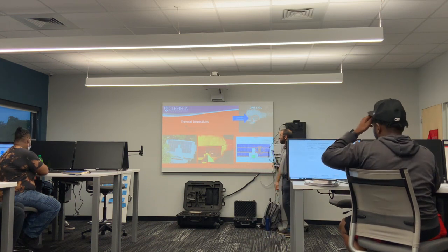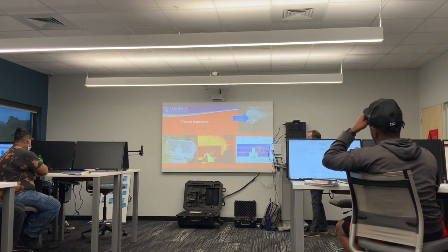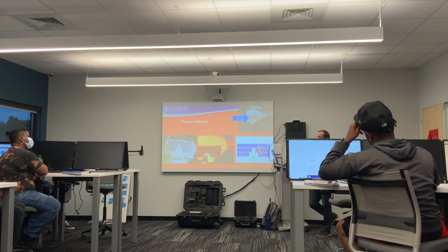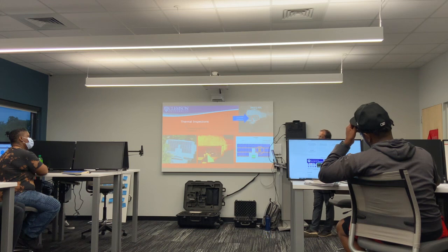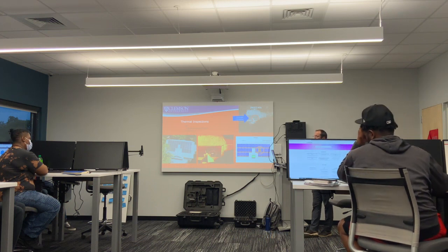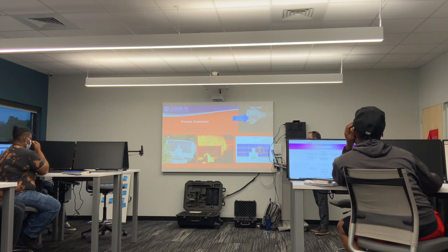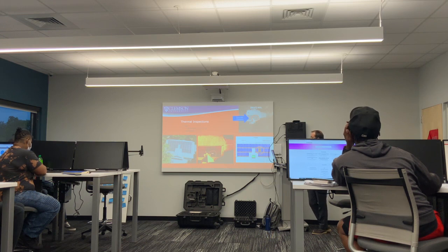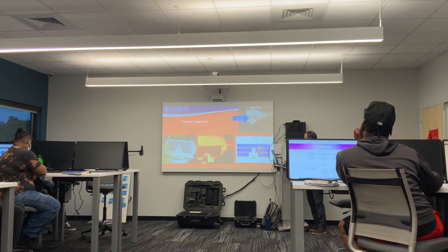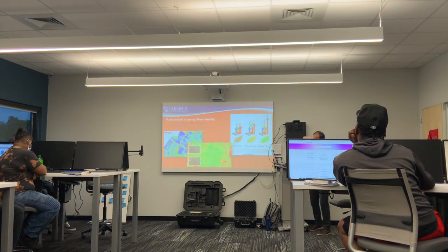So very interesting. He estimated, based on solar panels that he flew around Clemson's campus, that there's probably 20 to 30% that were damaged in some way, which, you pay that much for solar panels for them to just fail. And there's really not much you can do other than maybe tracking it like that, but there's probably some defects that you won't even be able to see with that back end that you might only be able to see with a thermal imager.